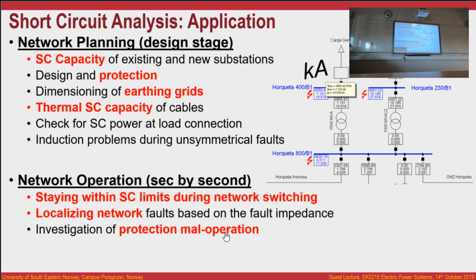I mean, we are working on something called intelligent and smart protections that are able to adapt to the system. However, at the moment, if you go to a substation, you need a protection, and that protection requires a setting. From 2 amps above, that is a fault. 2 amps below, everything is fine. And the person responsible for that calculation, hopefully, will be one of you, okay? Well, I don't know if I say hopefully or not.